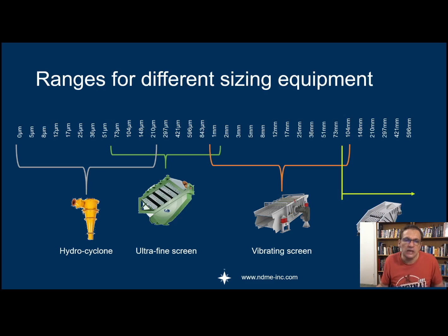Now, in general terms, different devices work best for different sizes, i.e. hydrocyclones work well down to about 250 micron. There are unique cyclones, like flat bottom cyclones, that invade this space. And of course, it's all dependent on the SG of the particles. Remember that a hydrocyclone is a hydraulic separation device more than a pure size separator. You just use hydraulics to do the size separation.